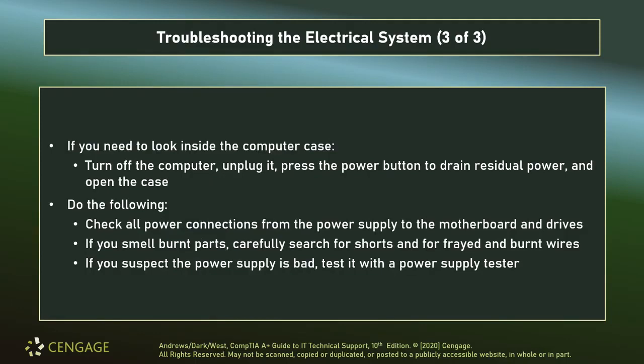Now, if you need to take a look inside the computer case, we always want to follow our standard disassembly procedure. Turn off the computer, unplug it, discharge it, and open the case while remaining grounded. So either keeping your hand in contact with live metal or wearing an anti-static strap, which tends to be a much better idea. Of course, check all your power connectors, look for burnout parts, look for potential shorts or little scorch marks on the motherboard itself.